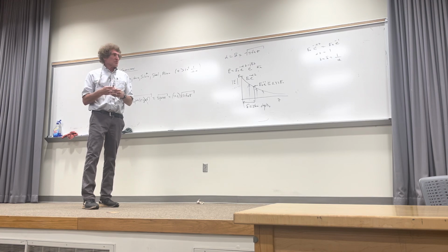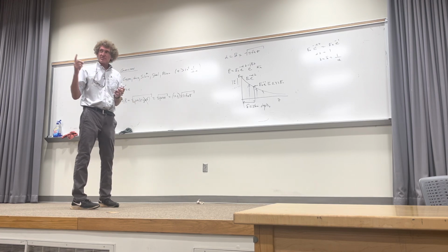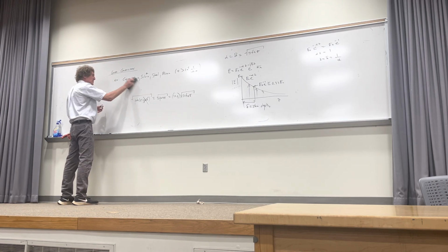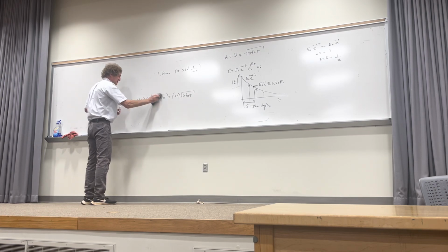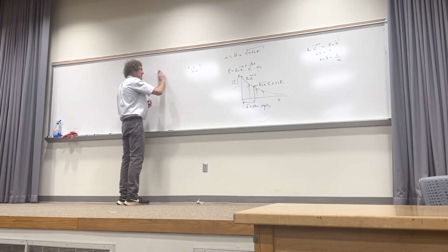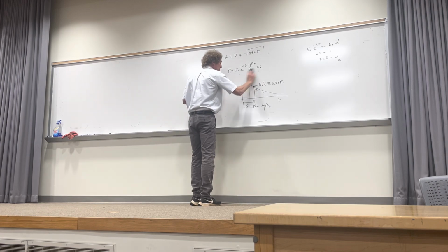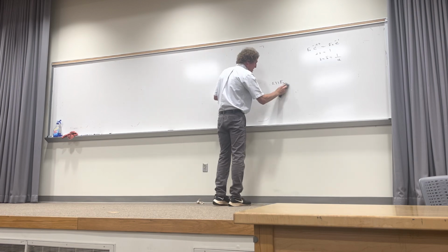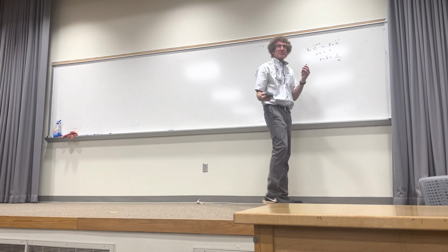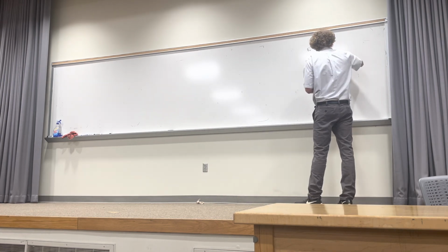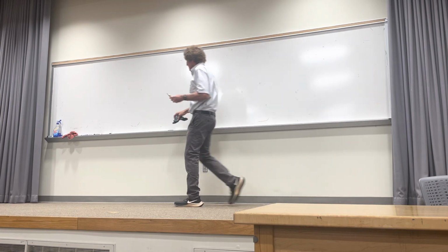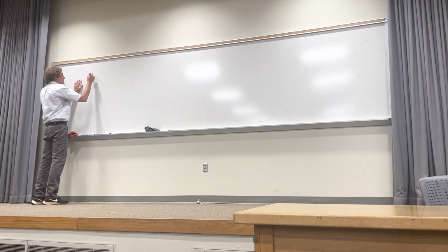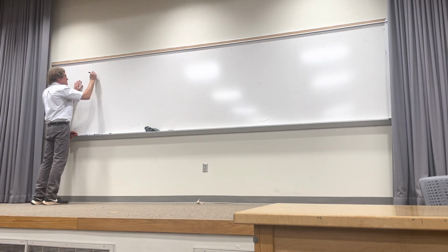So, how is this term skin depth useful to engineers? And here's the big thing. Now, there are proofs, and you can actually prove what I'm going to do in a much more involved way, but it really doesn't shine light on what it's useful for. And again, this has to do with the material you're propagating through. The skin depth, like the loss tangent, is a figure of merit for the material. But this is for good conductors. So, here's the biggie with skin depth. And it's AC, or high frequency resistance.